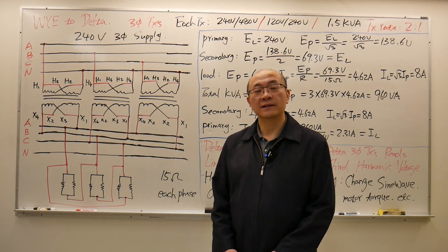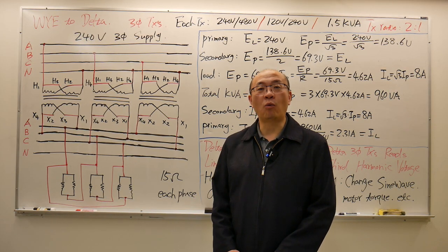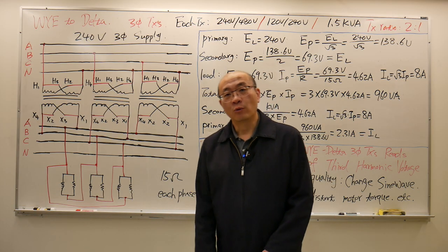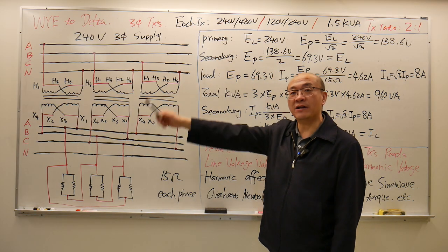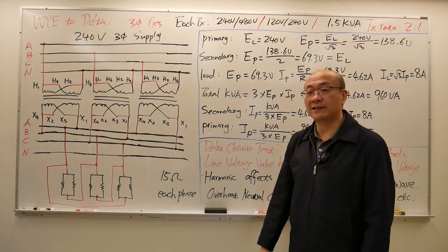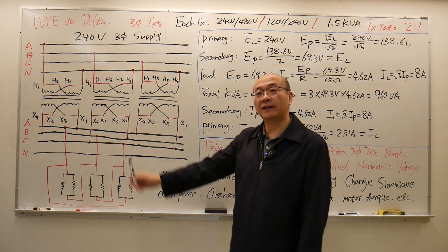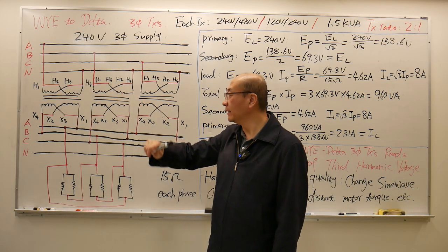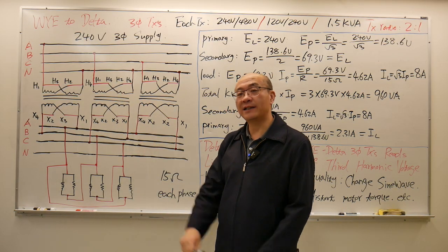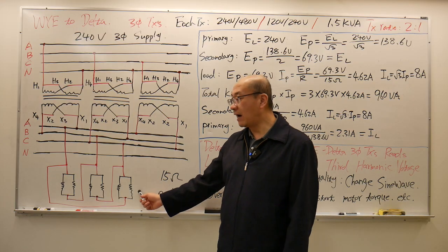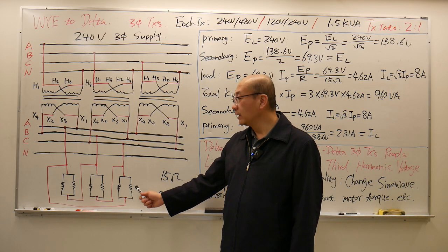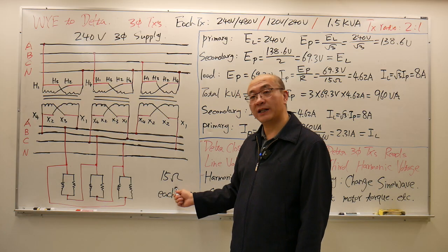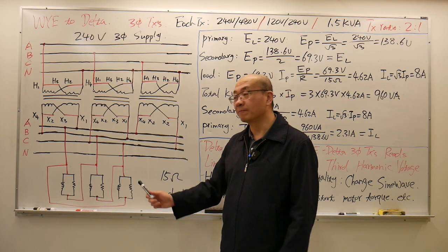Hello everyone. In this lab we're going to talk about the Y-delta three-phase transformer. We still have the same transformer bench. Each transformer's rating is the same, but this time we connect the transformers in parallel Y on the primary side and parallel delta on the secondary side. We also have a three-phase load of three 15-ohm resistors connected in delta.